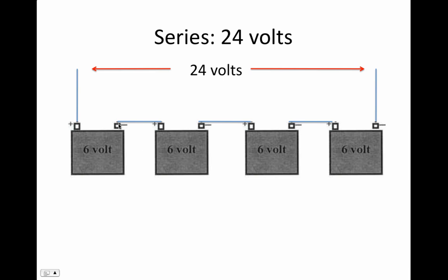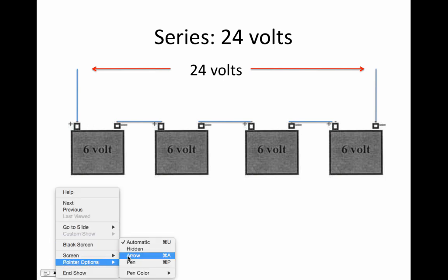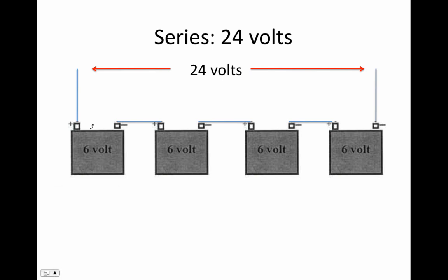Now, one thing is very, very important to remember for safety around batteries is that you never, ever want to connect the positive of one battery to the negative of the same battery, because that'll create a short circuit and something bad will happen. You may get burnt. There may be an explosion. Depends on how big the battery is and how strong the connection is that you make across here. This is a very bad safety problem, and I'll just make sure that we understand that by saying never connect this to this. Never, ever do that, even by accident.